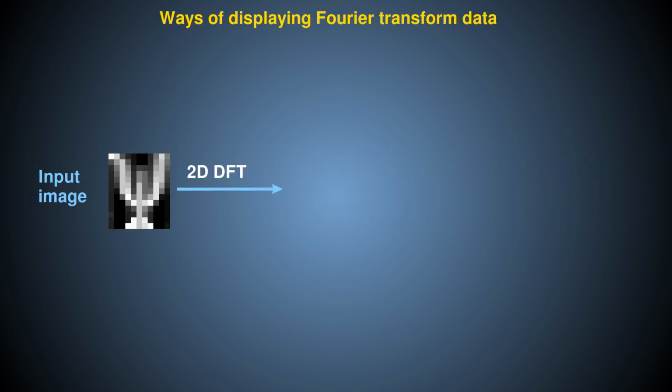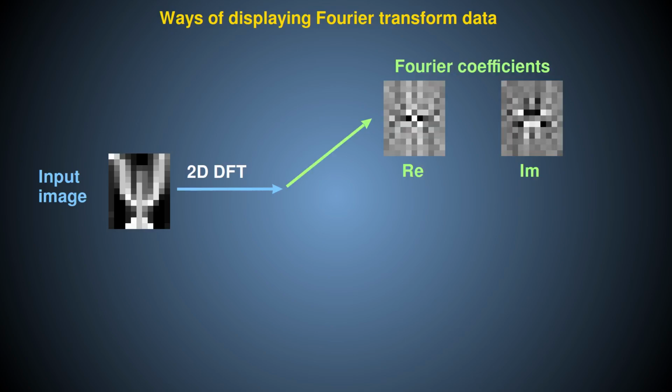The reason the DFT in the previous section didn't look like the ones some of you might have expected is that most people, when they display a Fourier transform, don't display either or both of the Fourier coefficients. Instead, they display a plot which captures the absolute strength of each harmonic in just one number per harmonic. Not only does this mean you don't have to switch between two components all the time, but also it gives an instant visual sense of how strong or dominant a particular harmonic is in comparison to all others. This overall measure of strength of a harmonic is called its power.